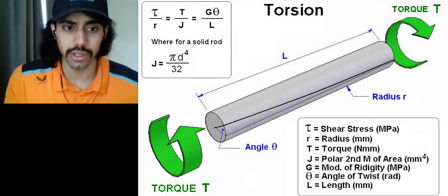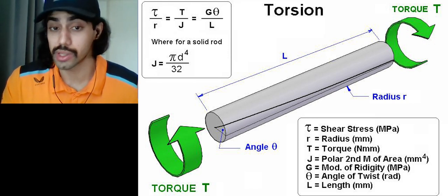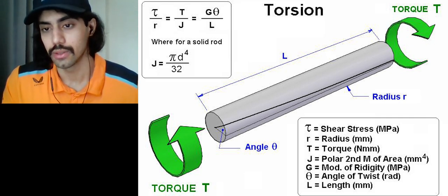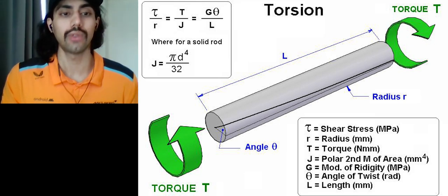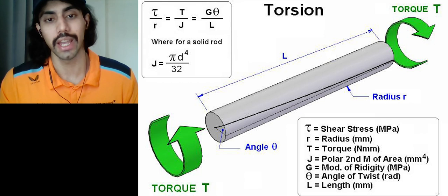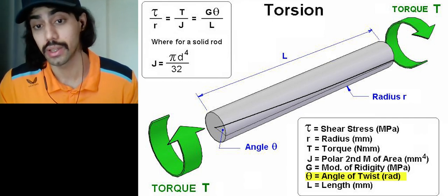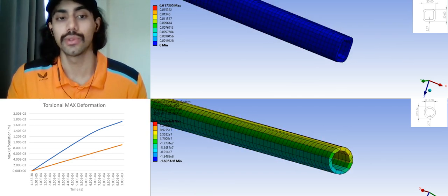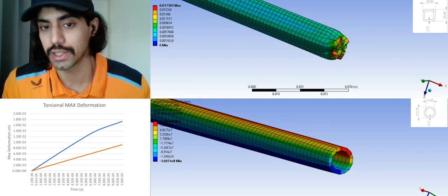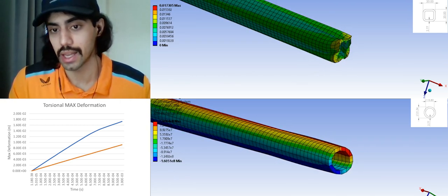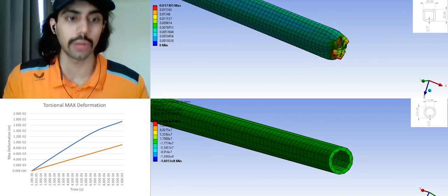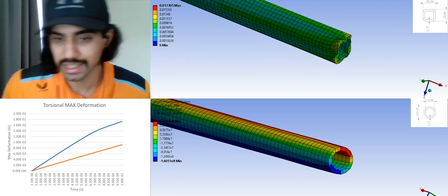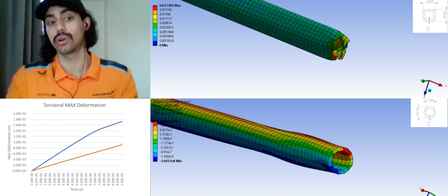The next critical parameter is torsion, which plays a vital role especially in joining parts where pipes are welded to each other. Firstly, we should understand the crucial factors to calculate torsion. We aim to find the delta, which determines the angle of twist. We will apply the same angular torque to our beam to determine which cross-section has more fatigue resistance against torque. As depicted in the diagram, the circular profile shows less deformation compared to the square shape, indicating that circular pipes have more resistance against torsion.